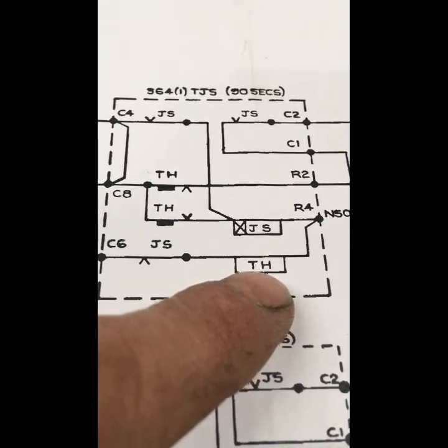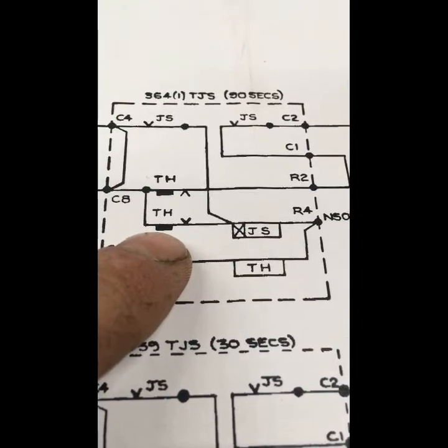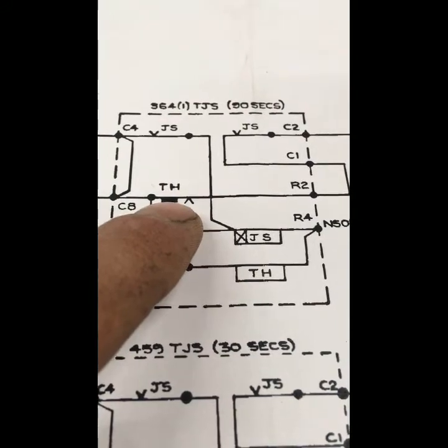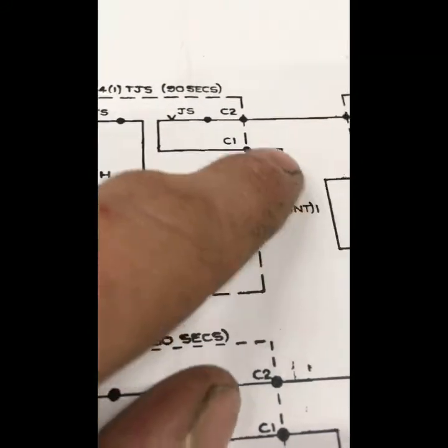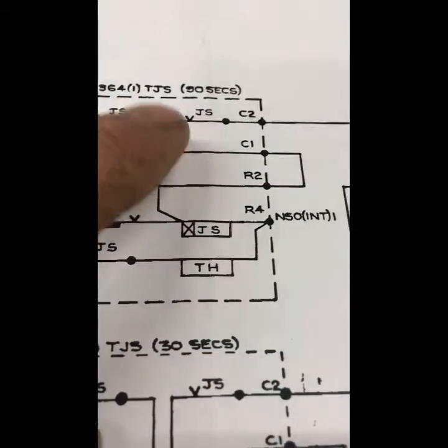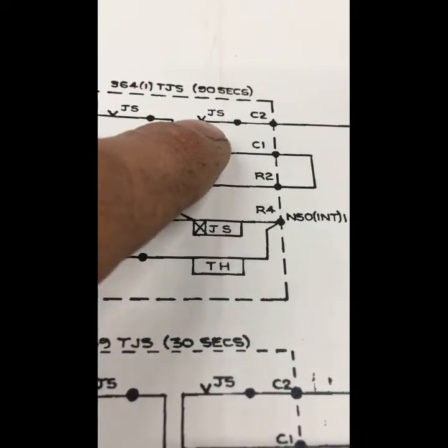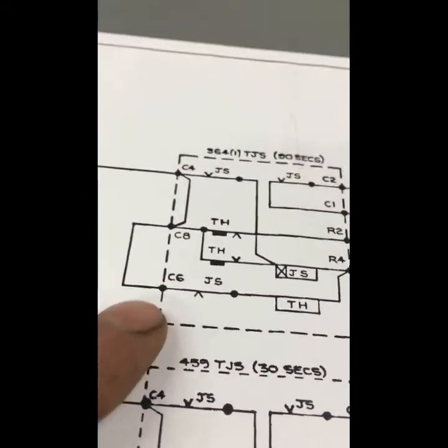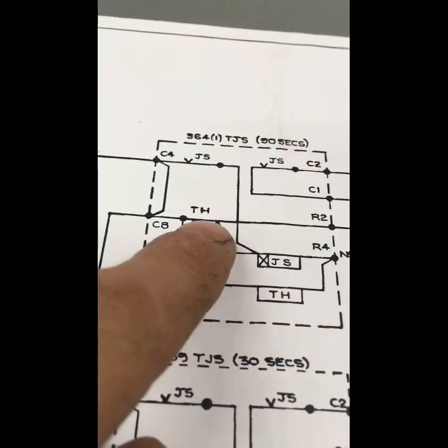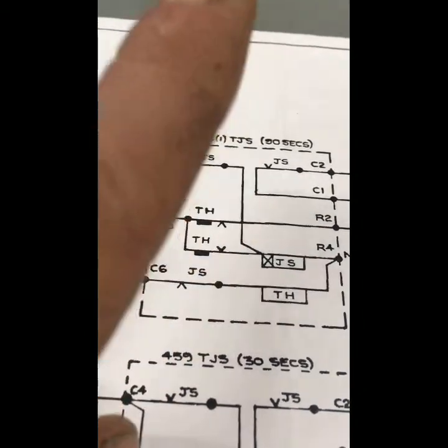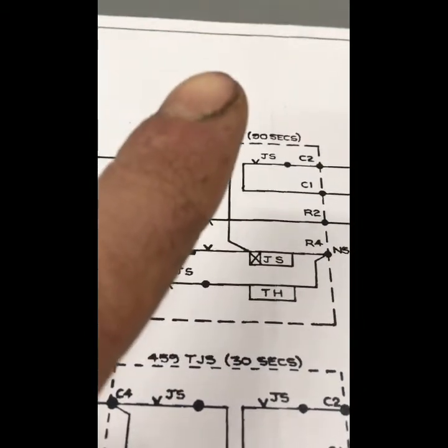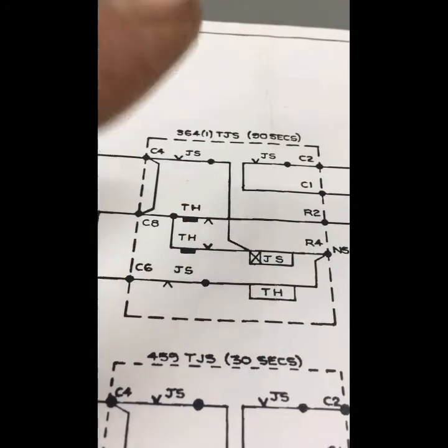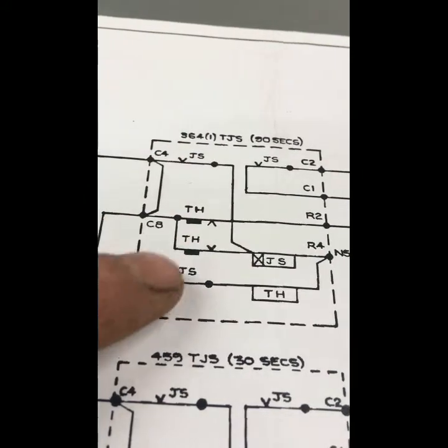As a bimetallic strip starts to bend, it will eventually bend upwards and make its top contact, this one. Breaking this contact, its back contact. As it breaks its back contact, it breaks off any potential feed through to output circuits. But it's already down as well, because this contact is still not made either, as is that one. So we started to heat, the back contact is broken, the front contact is now made. We have completed our circuit to making the timed part of the circuit that I mentioned, but as I mentioned, we have to cool it down again and go back to our original position.